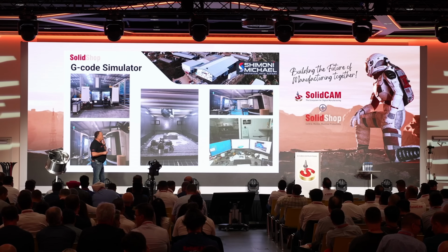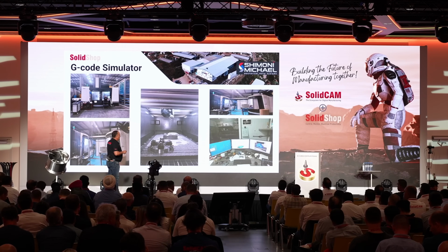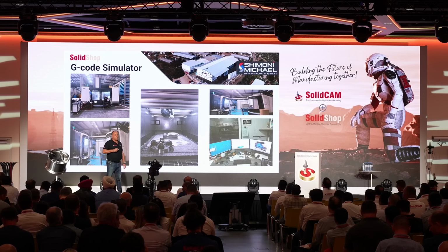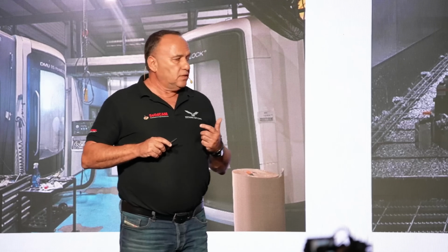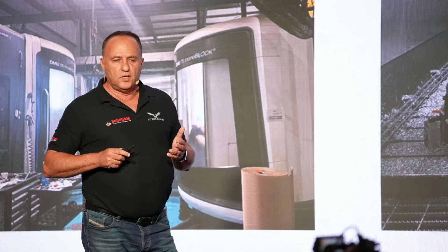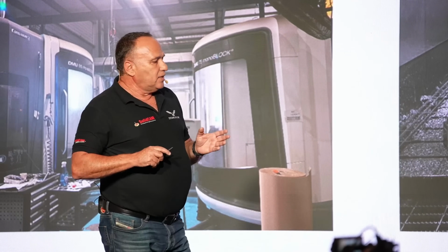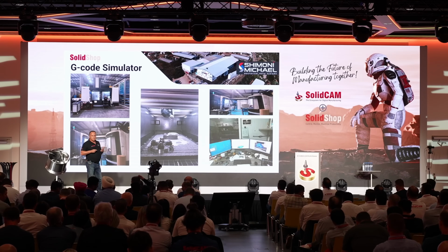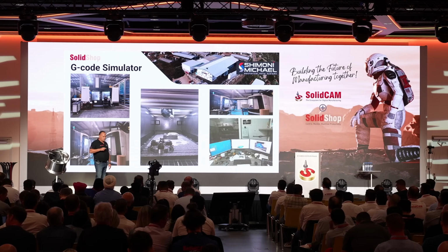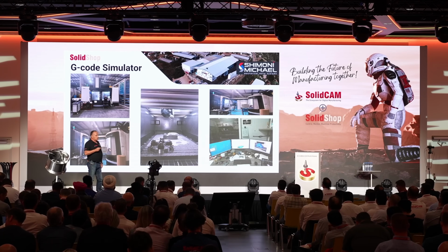G-code simulator. The G-code simulator is a fantastic module that we have been waiting for a long time, because it's not just the standard simulation of SolidCAM and all other CAM systems. It runs the final G-code line by line, so it means much more confidence for the customer. It can be almost 100% in the simulation before going to the machine.